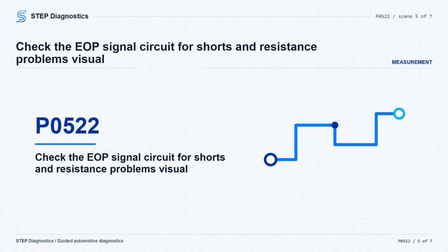Now isolate the EOP sensor pressure signal circuit. The ignition must be off when checking continuity to ground or checking continuity between circuits. Disconnect the ECU and every component connector that contains the circuit being tested, and use the wiring layout to follow the circuit path. If a PCM connector terminal needs to be accessed, do not probe the PCM harness connector directly. Use the GPEC Diagnostic 10436 adapter so the PCM terminals are not damaged.